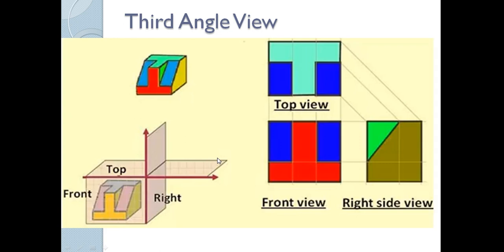The same goes for third angle projection. So again, you can see the difference. The plan goes on top of the front elevation and the right end elevation remains on the right and the left end will remain on the left.